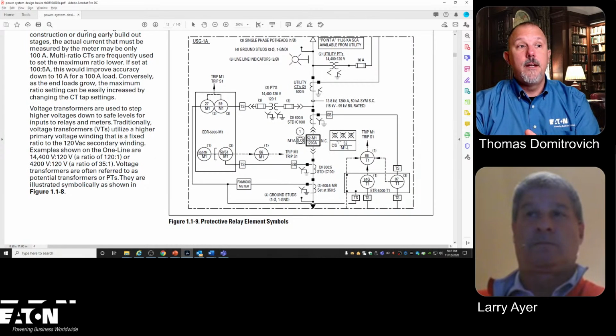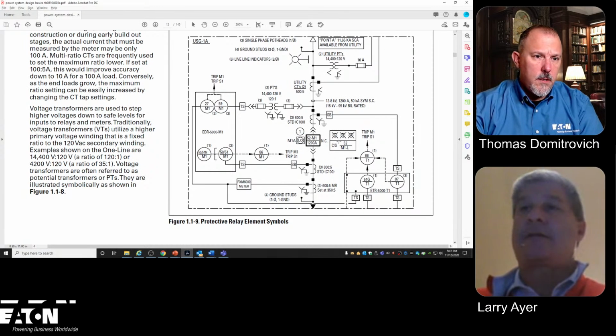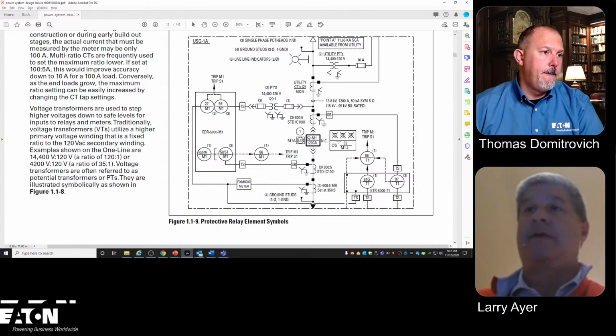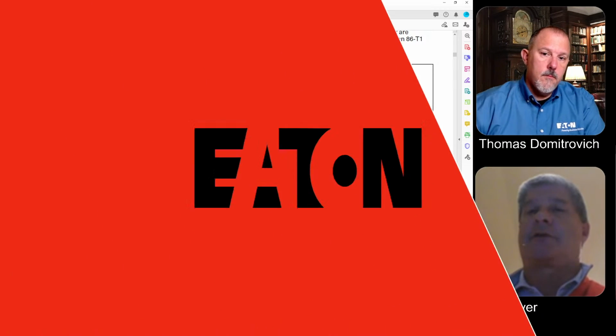But the fact is, it's important to understand you don't have to do that adjustment like you do on low voltage equipment. Well, I think the other concept is that in low voltage areas, the space is smaller. So when you get to medium voltage, the enclosures are larger. There's more room for the heat to escape. And I think that's part of the reason why you can get more with the 100% rating.